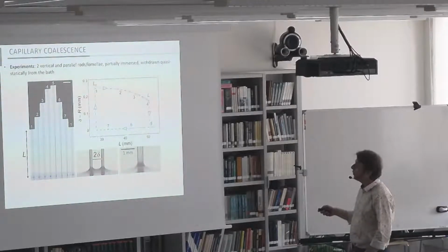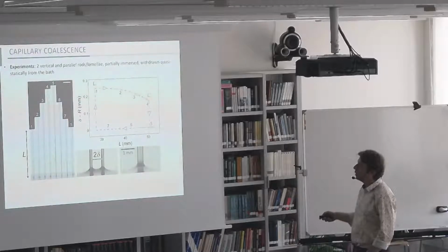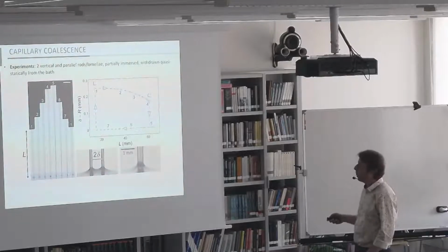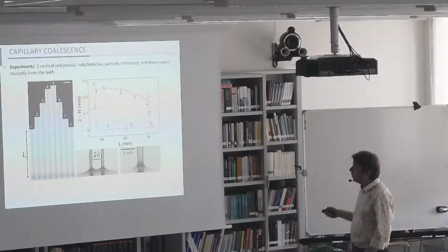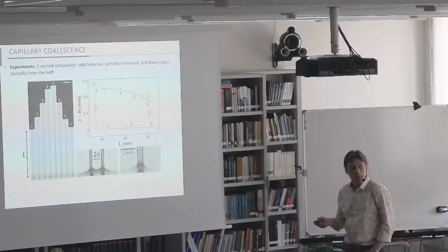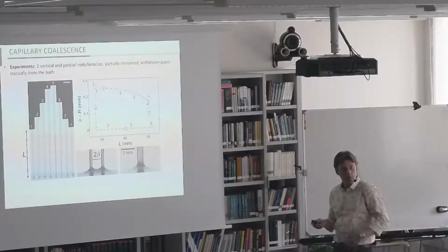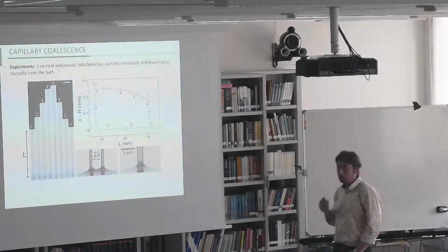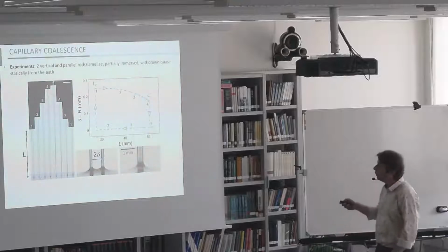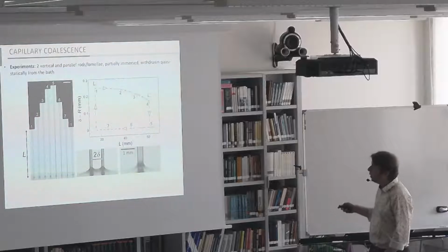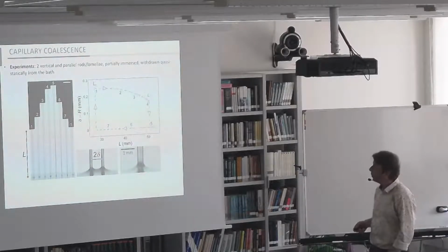And now you increase the dry length, as you can see here, and this distance between the two structures decreases until you reach a critical value of the dry length where they snap to contact. And when they are in contact, if you decrease again the dry length, they stay in contact until you reach a second critical dry length, and they go back to the previous branch. So you have here a subcritical bifurcation with a hysteresis loop and the coexistence of two stable states.